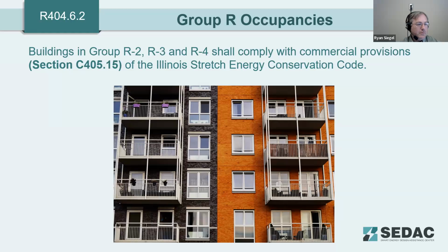So you can't just put a two pole breaker or 2-pole spot in your main electrical panel and say for future electric sub panel. You would have to install that sub panel at the time of construction. But good question on that.